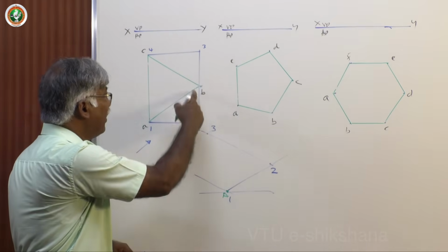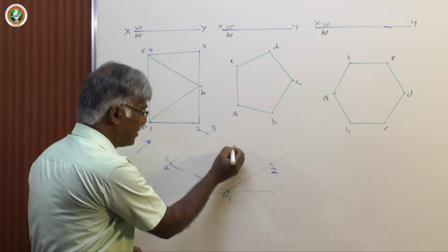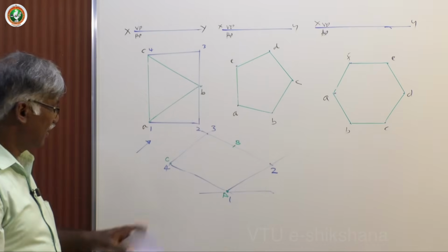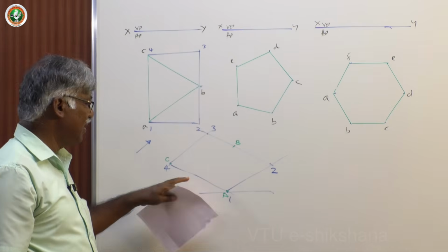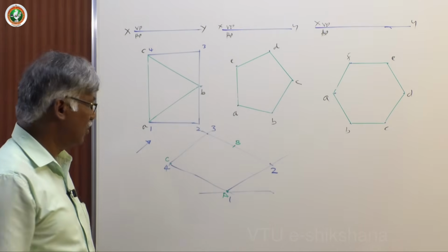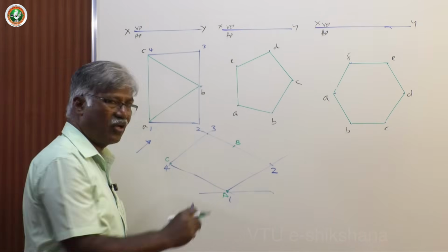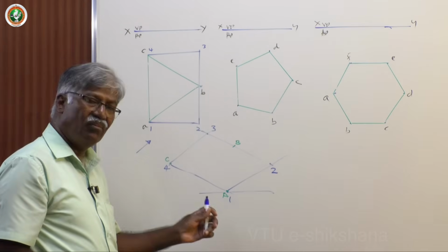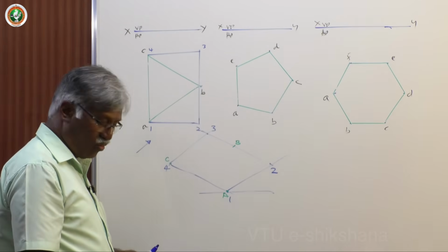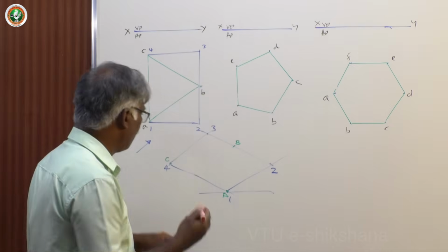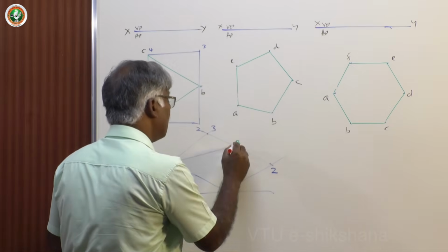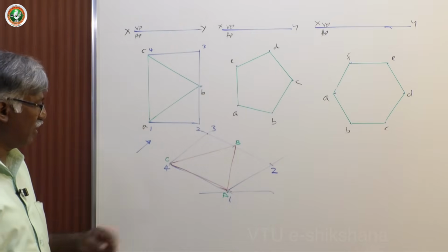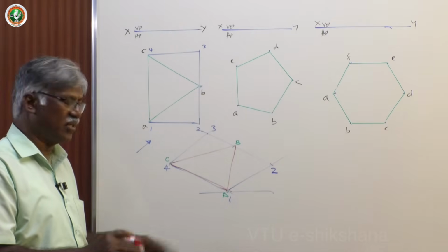Now the midpoint of 2, 3 is giving B. So in computer it's easy. Draw the rectangle, keep A and C ready, and if you move the mouse, then it will automatically come with the IntelliSketch if you have set the midpoint. Always it is there. Now this is the isometric view you are drawing of this. If you take the scale, this becomes the isometric projection.